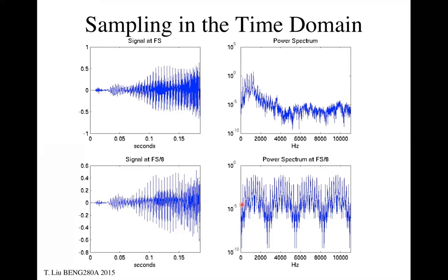You can see that around 0, in the low frequencies, if you compare peak to peak, they're reasonably similar. But then as we get to higher frequencies, something very strange happens in that the whole thing just repeats itself over and over. Out to about 3 kilohertz, we have this symmetric looking function around some center, and then the whole thing just repeats itself.